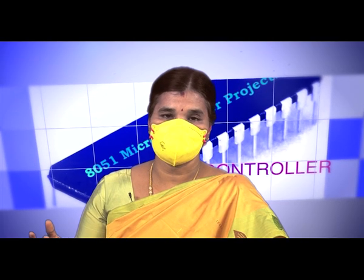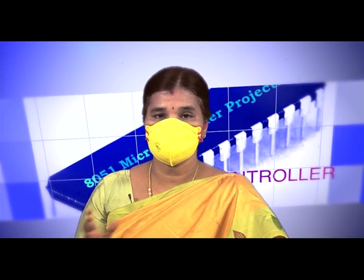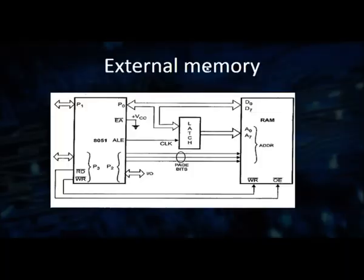So, during that external access, what are the specifications we have to follow? So, how do we interface the 8051 with the external memory? See this diagram, the left side shows the microcontroller. Already we have discussed, this is an 8051 microcontroller which has a number of ports, right. Then the control signals read bar, write bar, along with the two control signals which are ALE and EA bar. So, in which ports are the address lines and data lines available? Port 0 and port 2. So, that is why here we have taken only port 0 and port 2.